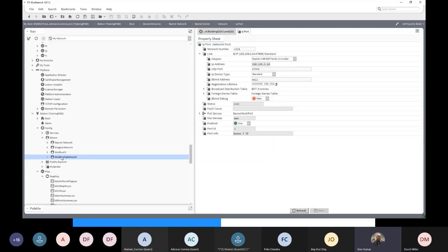How many protocols are allowed running in the FX80? By, I guess, how many integrations we can define? Yeah. So the limit is the number of physical ports. You've got 2 as standard. You can put expansion modules on to get 4 more. So you can get a total of 6 RS485 ports.